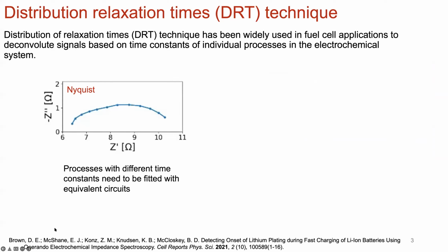So this is a very good recent paper, within the last few months, that came out on trying to apply this technique to fast charging and detection of NMC full cells with graphite, and detecting when lithium plating occurs, which is a common failure mechanism for fast charging.